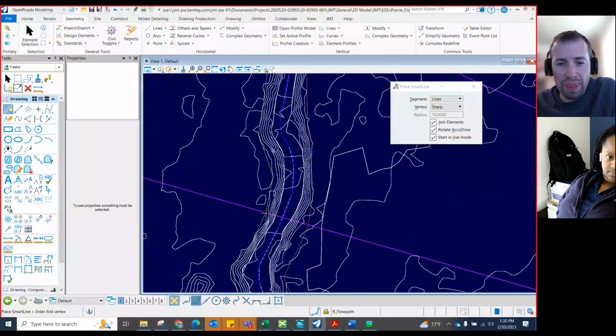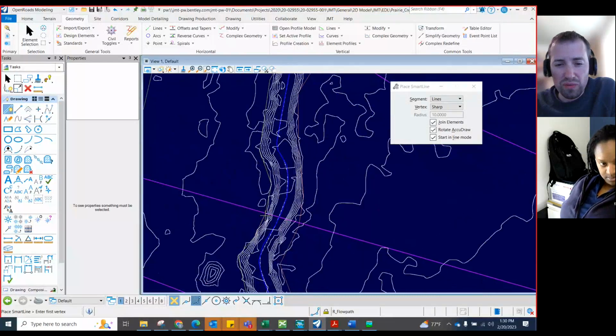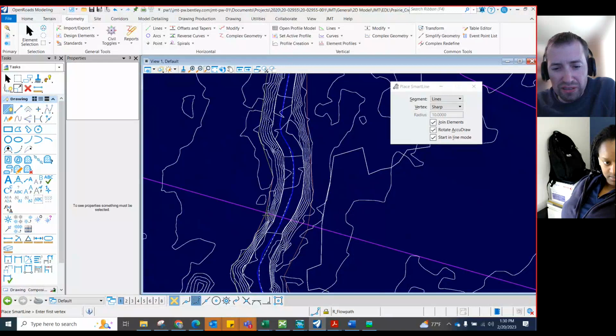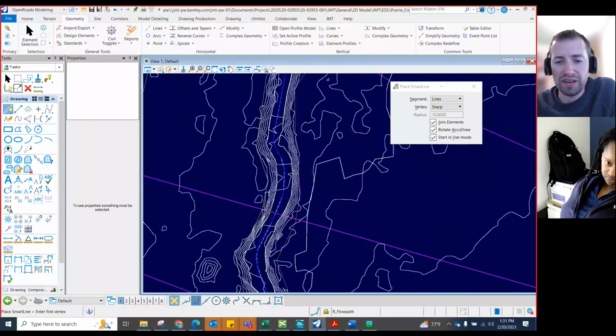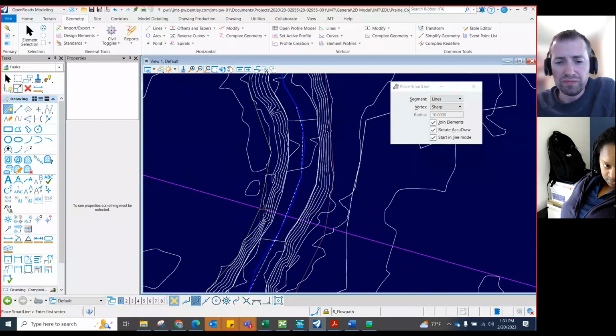And so if I got in the model and said, oh, really, it's over here, I could do that without needing to worry about this file being perfect. It doesn't really matter. If I wanted to change, say, that starts a lower n value, or that starts a higher n value, and this is a lower main channel, but maybe it's really right here, I could do that within the model itself.